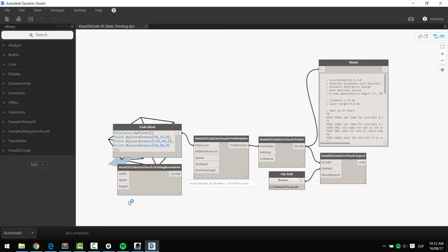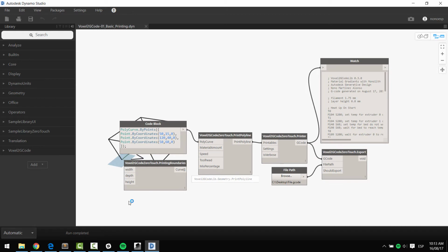So these things are not possible with normal slicers because they just want you to say, I want to print this object, and then at the other end you just get the object printed. But you don't know anything about how much material, how it's behaving, how much it stops between layers, or things like this. Here, what I'm trying to do is make it possible to customize those, and this allowed me to prototype a lot more because I can basically draw by hand a polyline and see how that translates, tweaking the values directly. And that was a really valuable thing.